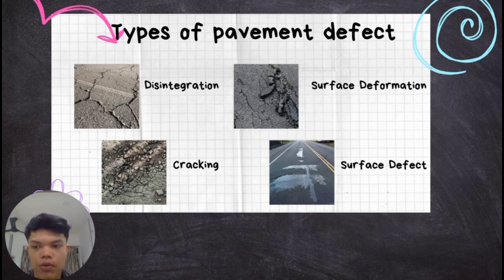Lastly, let's talk about surface defect. So, what causes surface defect? According to a resource, they are mostly caused by water ingress, freeze, and excessive usage from heavy traffic. Over time, defects such as cracking, edge failure, subsidence, or stress fractures may develop, all of which require specific road maintenance solutions.